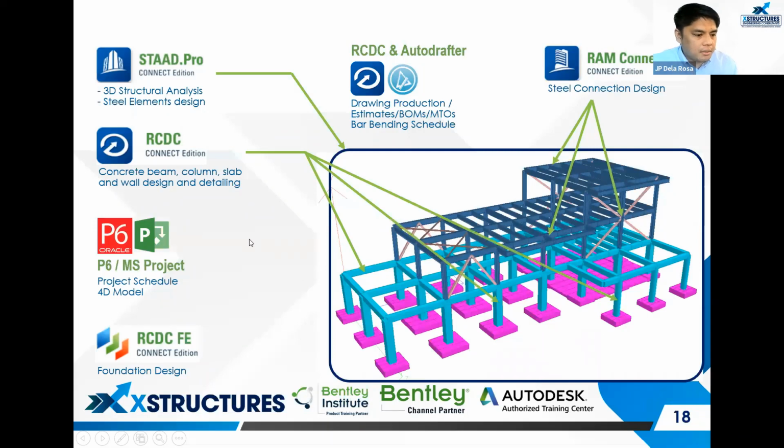Then RCDC will do the beam and column design, including the slab as well. And then RCDC FE, the new program, will handle the foundation design: isolated footing, combined footing, even mat foundation, or a piled raft or piled mat foundation, that's possible with RCDC FE. And then RCDC and Autodrafter will take care of the drawing production, the estimates, as well as the bar bending schedule.